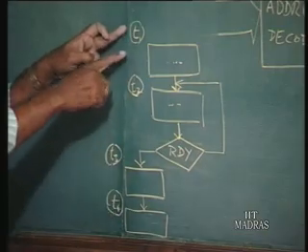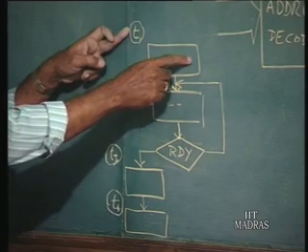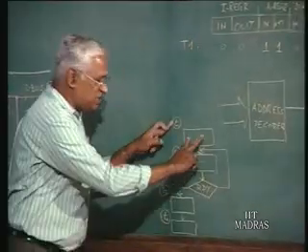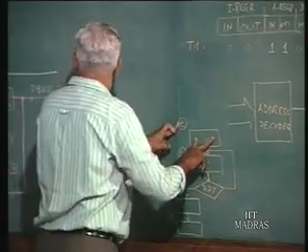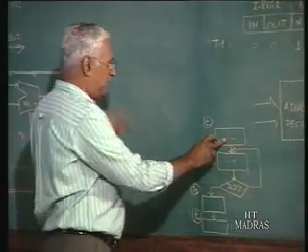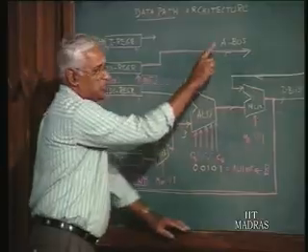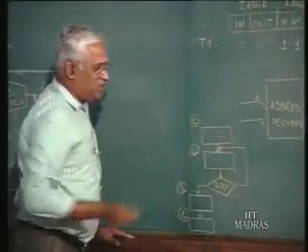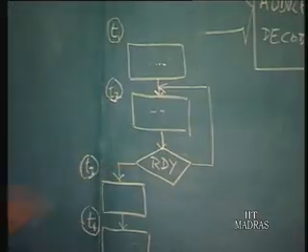During T1 the output that is generated will be this particular code, which enables the PC contents to be routed through the A register to the address bus, which we saw in the previous lecture. And also we introduced a ready input signal.